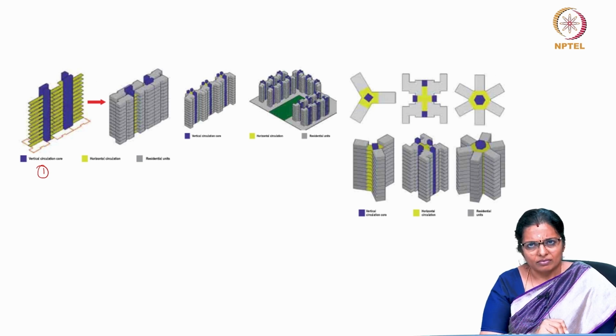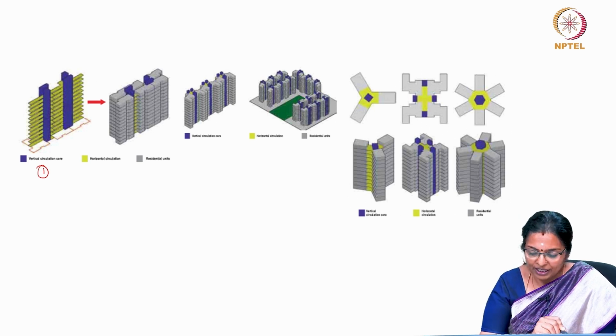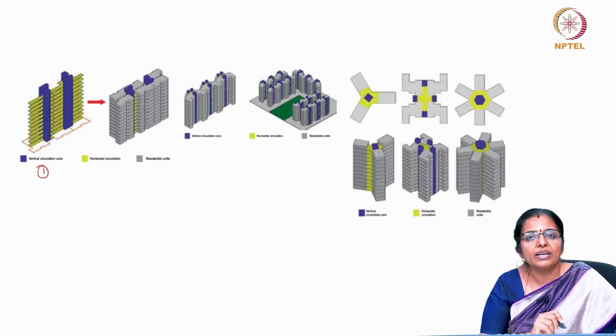So, the shape and volume of buildings should be compact, yet somewhat elongated along the east-west axis. Example, the optimum shape is probably in the ratio of 1:3 in hot and dry climates. The surface to volume ratio of the building should be as low as possible to minimize heat gain.